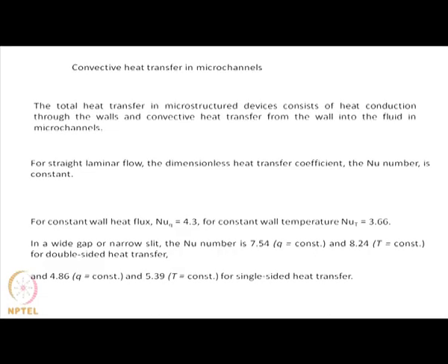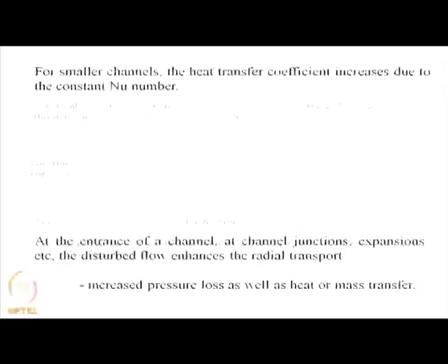Secondly, as I said, for straight laminar flow, the dimensionless heat transfer coefficient is a constant and it is 4.3 or 3.66. For a wide gap or a narrow slit, the Nusselt number can vary for double sided heat transfer, and for smaller channels the heat transfer coefficient increases due to the constant Nusselt number, as I have already described.